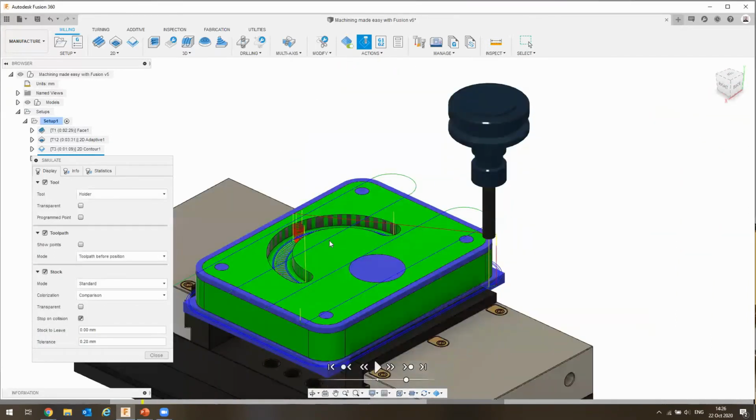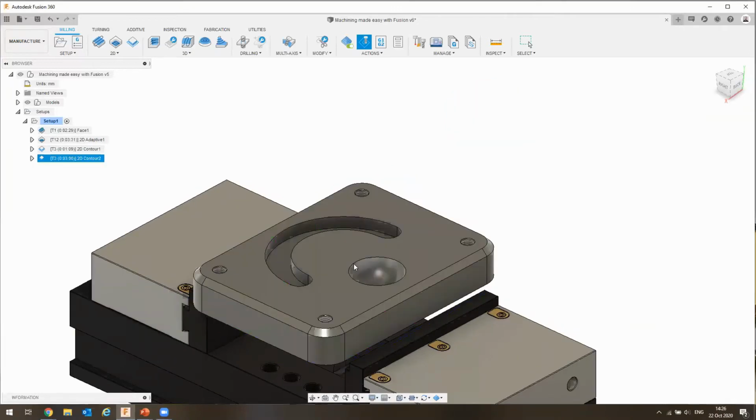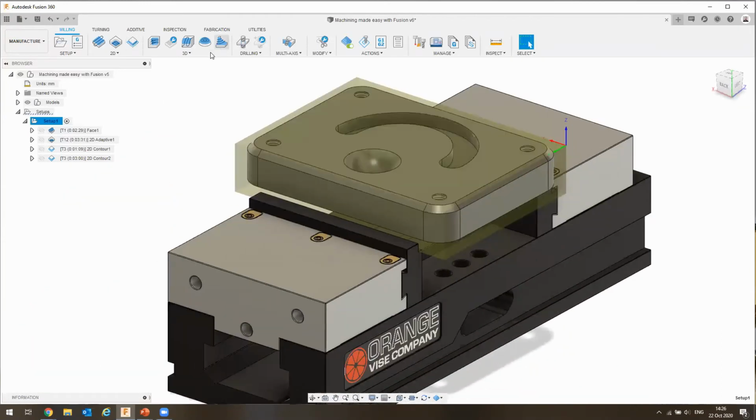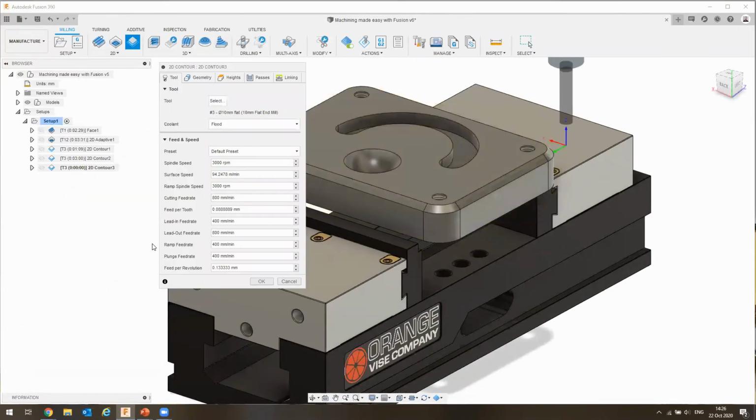So this is all done, this is done, but as you can see, we got this purple ball in the middle and we've got the 4 holes, and I haven't done a chamfer. So let's do the chamfer. So with that out the way, let's go and say 2D contour. This time I do want to select this edge.